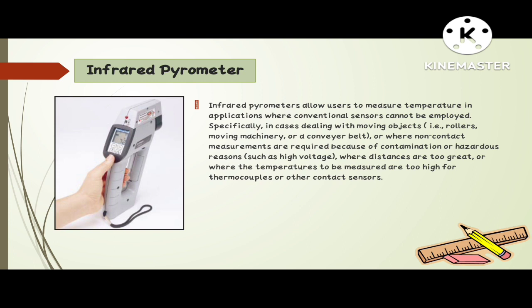Infrared thermometers work based on a phenomenon called black body radiation. Anything with a temperature above absolute zero has molecules inside of it moving around. The higher the temperature, the faster the molecules move. As they move, the molecules emit infrared radiation, a type of electromagnetic radiation below the visible spectrum of light.